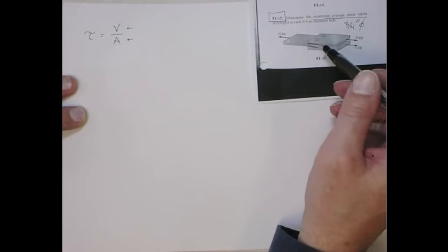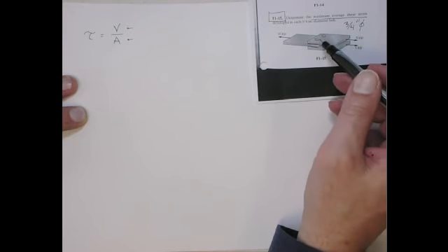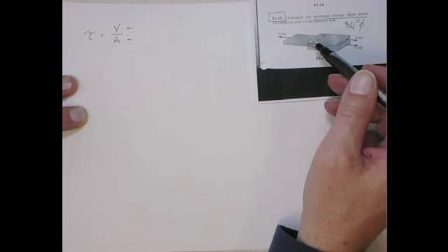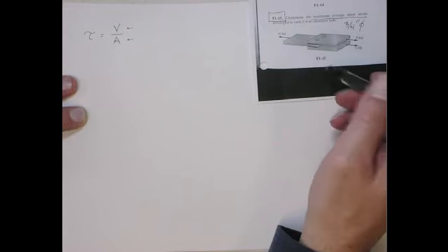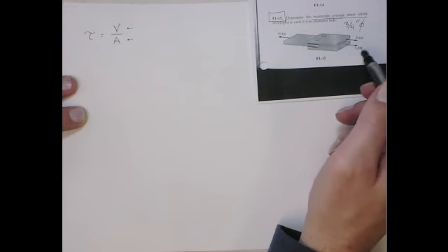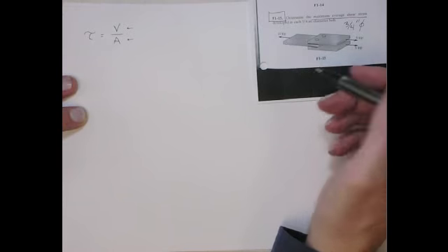If you look at it, there is no asymmetry that would say this bolt carries less force than this bolt. So we can assume them each carrying half of this 5 kips on each plate on this side and 10 on this side. You also notice that obviously the two 5 kips balance the 10 kips, and this is again an equilibrium problem.